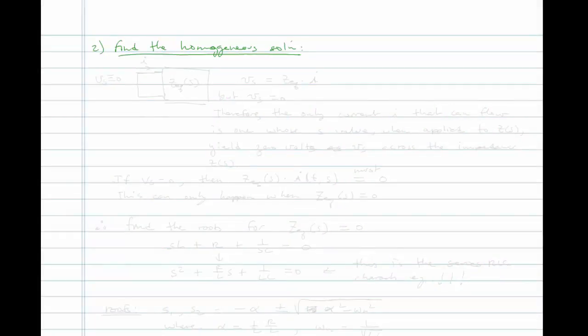Now this is a little more interesting, a little trickier maybe to visualize or conceptualize. So here's our network again. Now we're treating the case for the series RLC, but I'm writing it generally because what I'm showing you here applies to any linear network, not just the series RLC. So when we look for the homogeneous solution, we turn off the source. Vs is equal to 0, right? We force it to 0. And now we still have this current I.